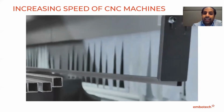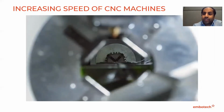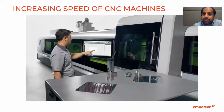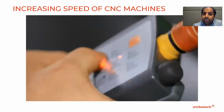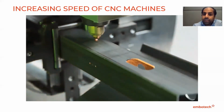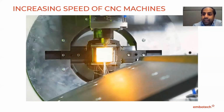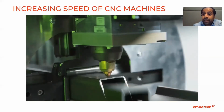And the other one, you can move over a long distance, but this is a little bit slower. And now the question is how to optimally split the movement along these two axes, so that on the one side you are really fast, but of course, as it is about cutting, you need to be at the same time very precise. And this is what we did also with an MPC-based solution using Forces Pro. And there we were also able to actually increase productivity by up to 10%. And this allowed the laser cutting company to actually deliver a solution which is much faster than what their competitors actually have.